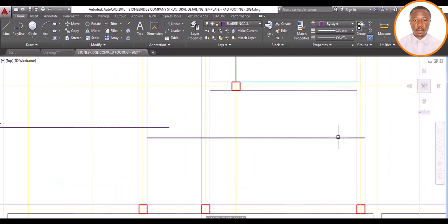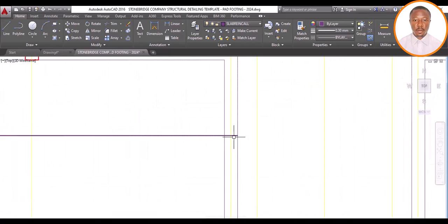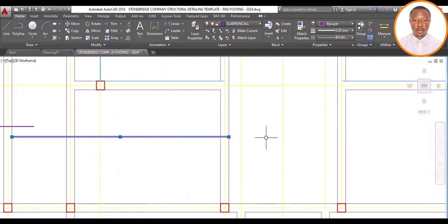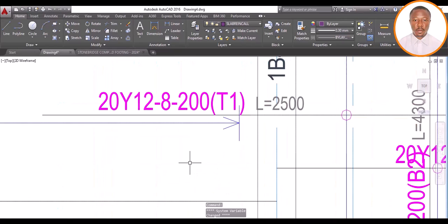Thank you. So this point here, I don't need to have my return bar because it's still within the slab. What I need to do, and at this point too, you can still enter this slab. So what I'll do, I'll move it by what? 600. Remember how we got our 600 into this particular slab. Is that okay? So now, which means that this reinforcement, this one from here like this, on this axis, I'm done with it. You can see how fast it is compared to what Prota detailing was giving us.